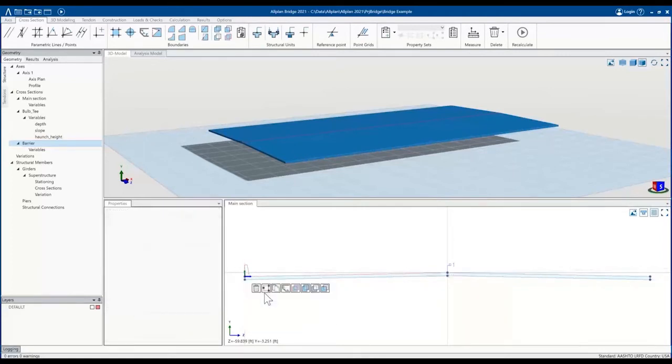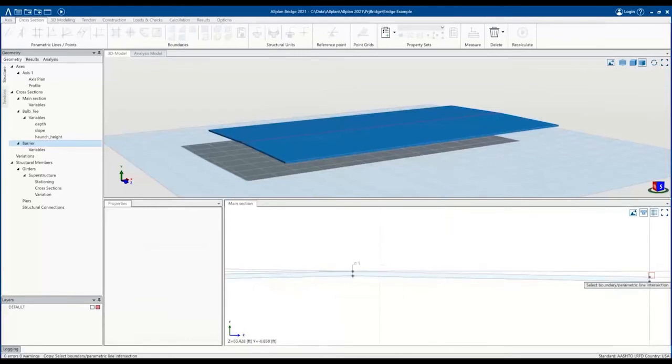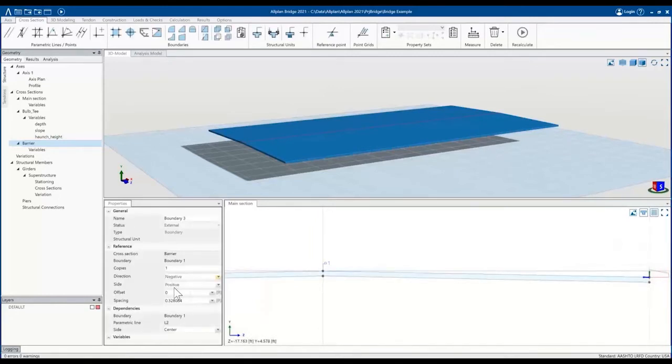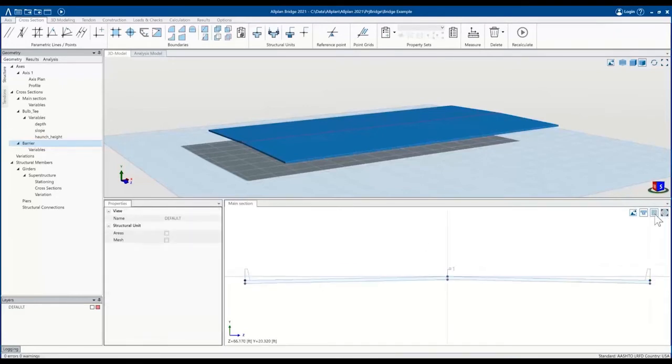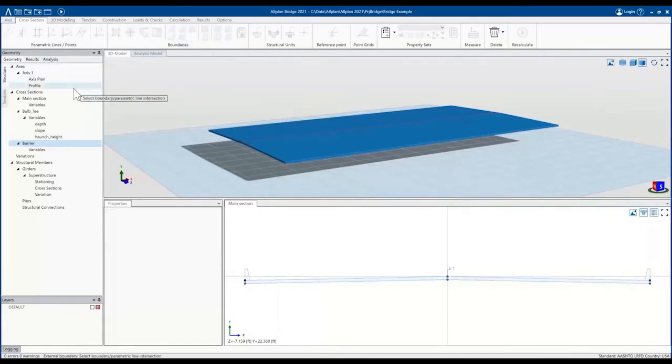When we place something in here in section view, it is going to be attached to the structural element that we're attaching it to, not only here in the CAD view, but also in the BIM platform, even as that element might change along its length. So barriers will be specifically attached to a bridge deck, even as it develops and loses super elevation. Let's go ahead and bring in our bulb T's, which are going to be attached at the bottom of the deck.